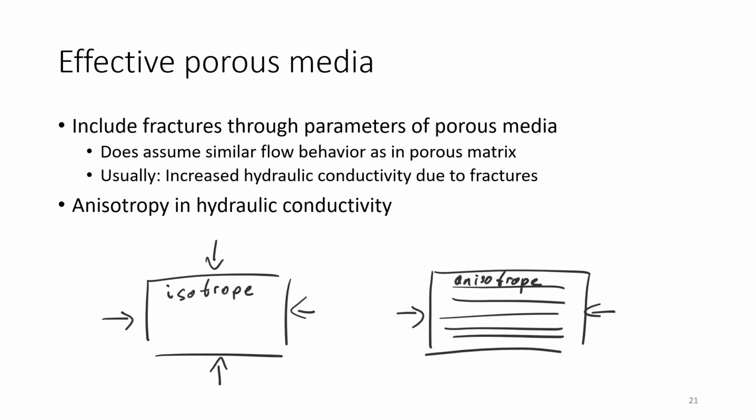So the effective parameter approach, this is what we have used almost all the time. You know, Darcy's law is generally valid. That's what you assume here, right? So there is no turbulent flow in the fractures usually, you know, all that kind of stuff. You only change the parameters, right? And if you have a fracture or a fractured area, you assign a higher hydraulic conductivity, maybe higher porosity, and that's it. Okay, you don't go any further.